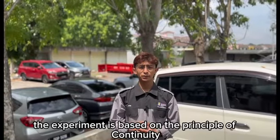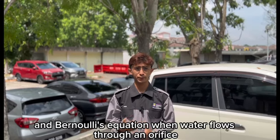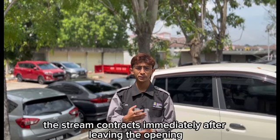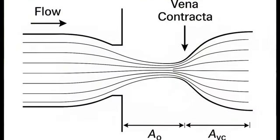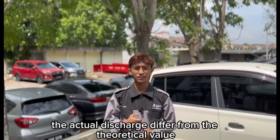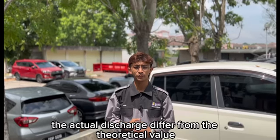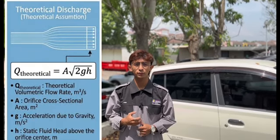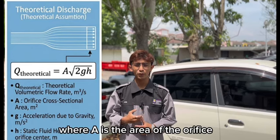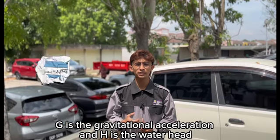The experiment is based on the principle of continuity and Bernoulli's equation. When water flows through the orifice, the stream contracts immediately after leaving the opening, forming a region known as the vena contracta. Due to this contraction and energy losses, the actual discharge differs from the theoretical value. The theoretical discharge is calculated using Qt = A√(2gh), where A is the area of the orifice, g is the gravitational acceleration, and h is the water head.